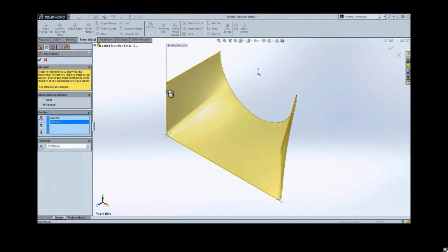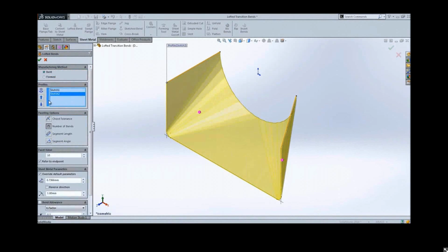So this is another scenario that affects the manufacturing process pretty greatly, when you do a lofted bend sheet metal part. Although SolidWorks has always had the ability to create these formed methods, in 2014 it now provides us an option to show these features as a bend or a transitional state. So if you have multiple bends to achieve that, we'll look at that.